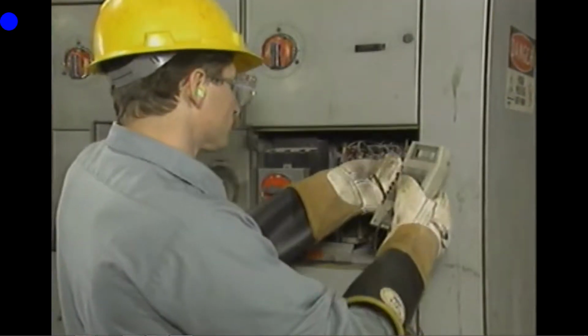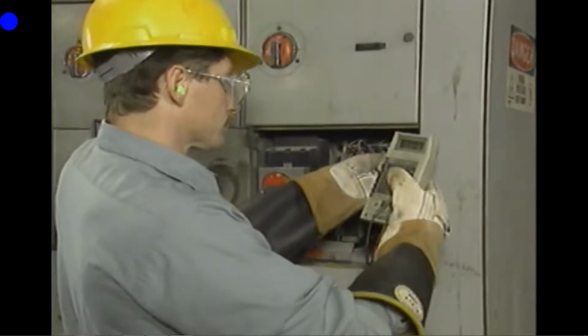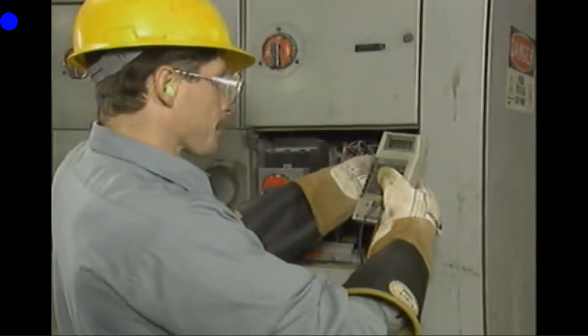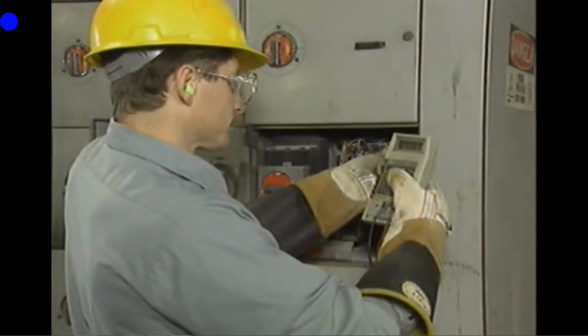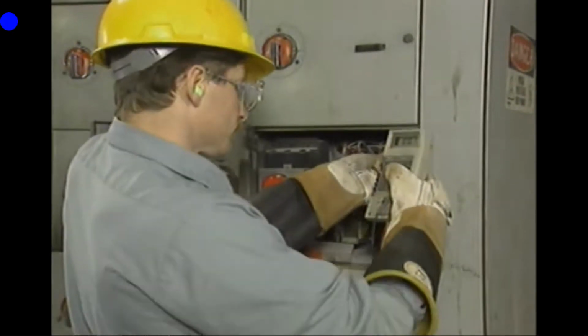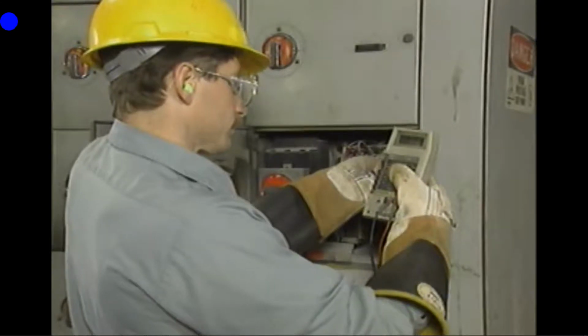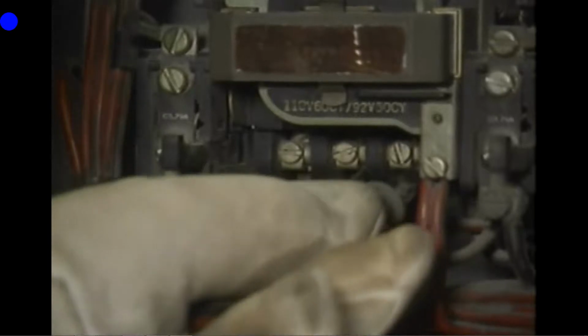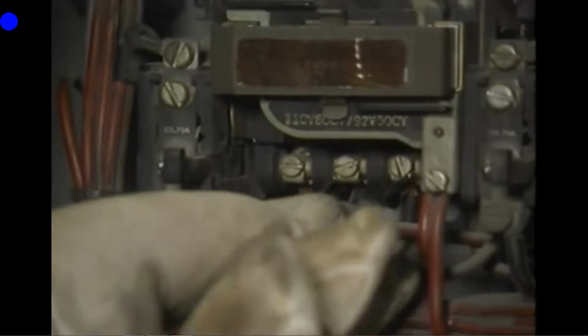After the repairs are made, the last troubleshooting task is to test the controller to make sure that it is operating correctly. To test a controller, you should operate it through all of its different operating modes to make sure that everything is operating the way it should and that there are no other signs of problems. While you're testing, pay special attention to any replaced or repaired components to ensure that they are operating correctly.